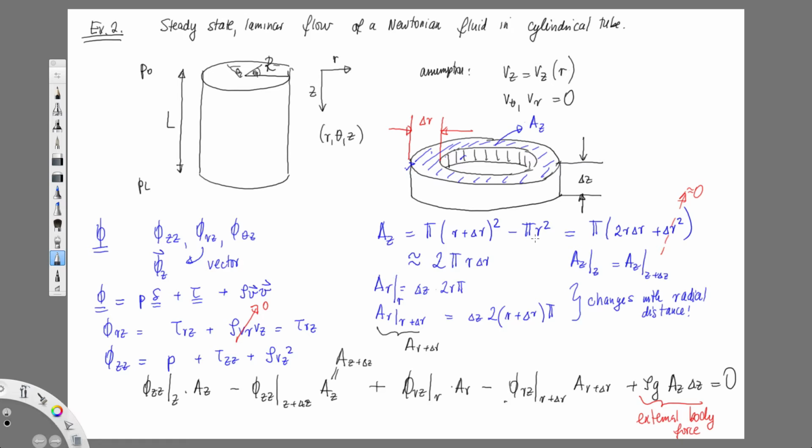Water itself is very much Newtonian. It's what we think of when we think of a Newtonian fluid. However, if that water is actually a drilling fluid, and it's carrying a lot of particulates with it, then it's possibly bridging into a non-Newtonian fluid. So you have to be aware of what is the fluid that you're dealing with.